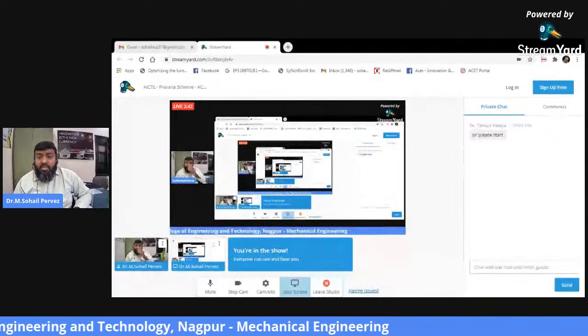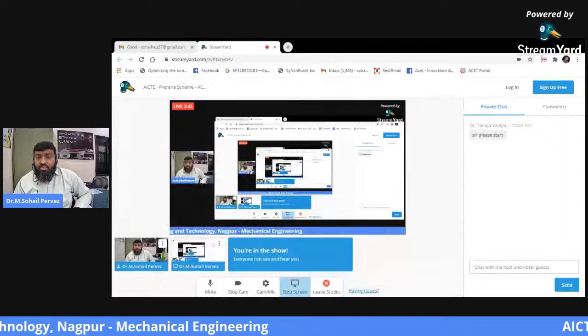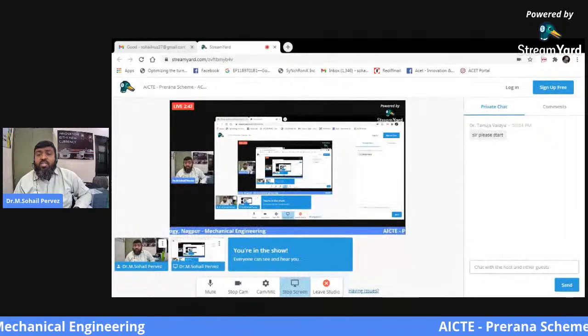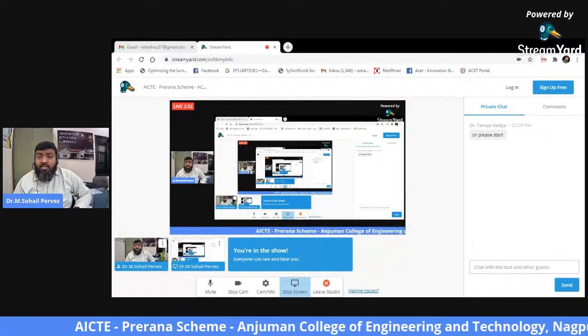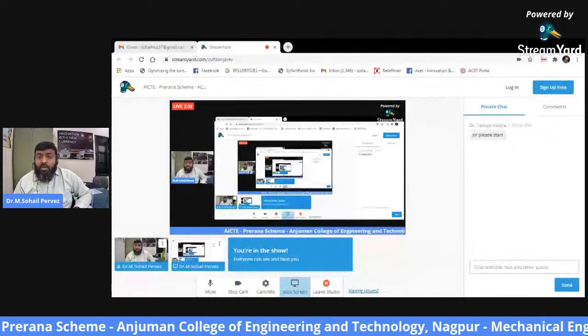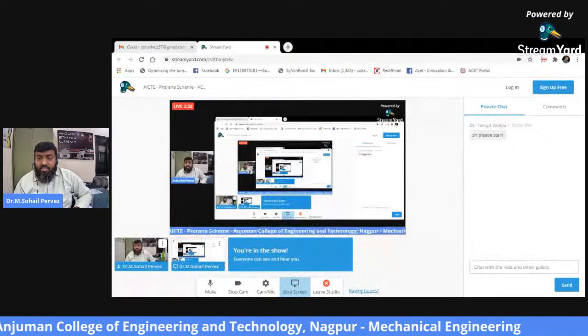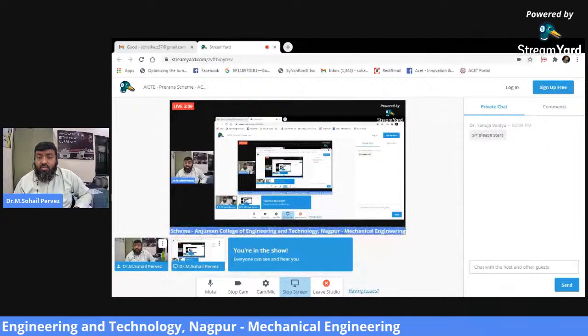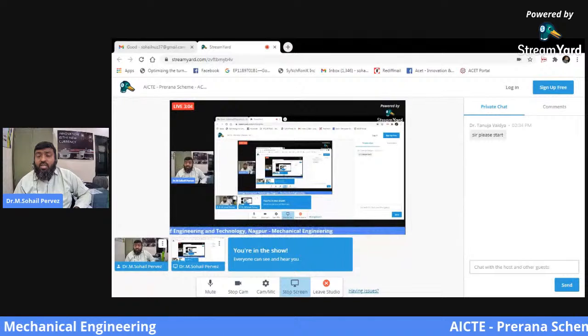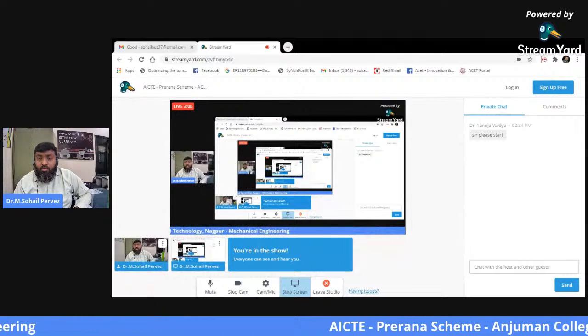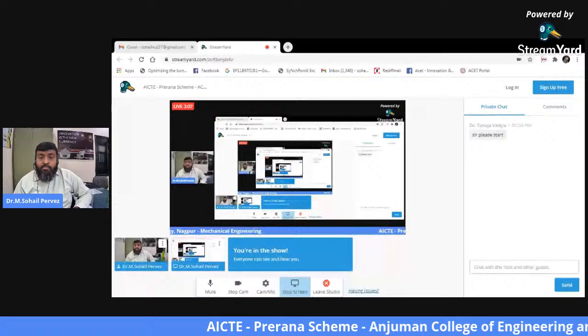So this BD, if you are concentrating, is known as the throat thickness. This is very important because BC and AB are nothing but the size of plate or size of weld, as it is generally called. Now, solving this triangle will give us the throat area, which is more vulnerable to failure.